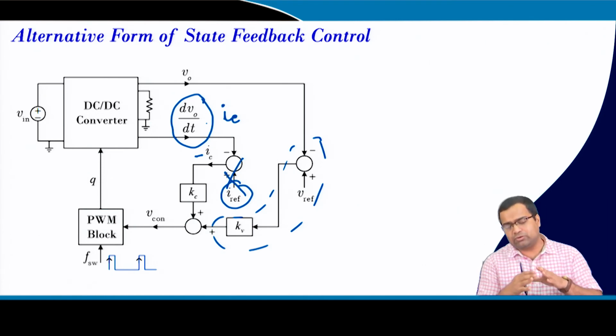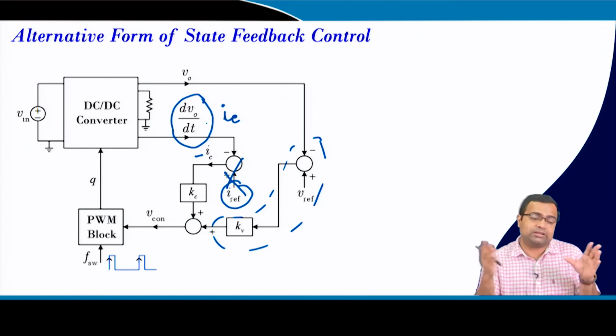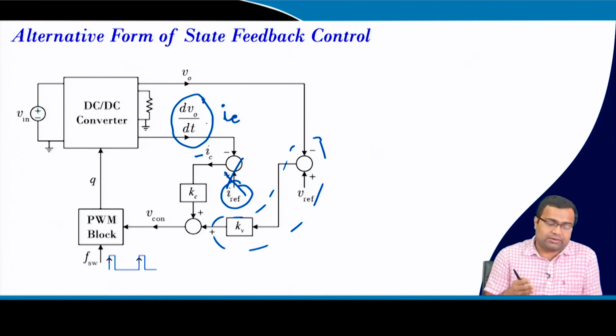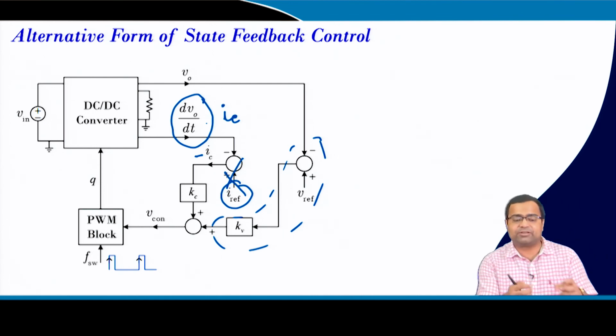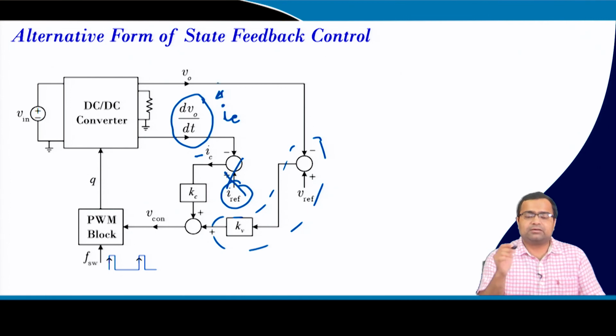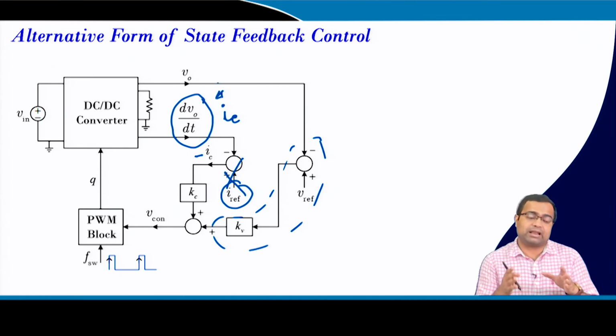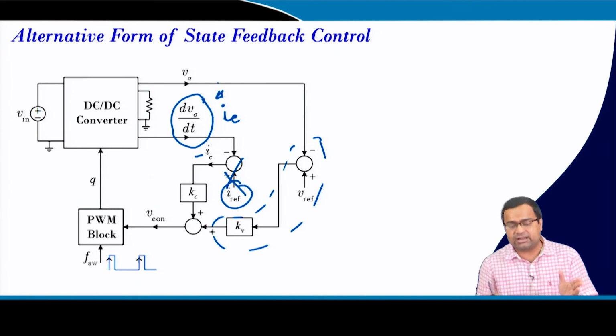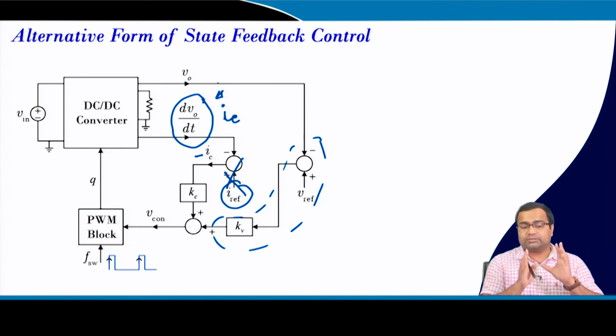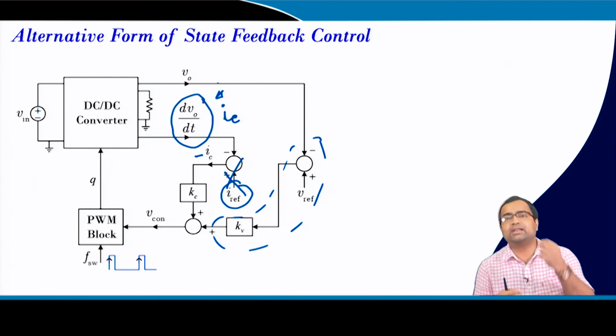And if we put a low pass filter, then we cannot capture the high frequency current information, because the low pass filter will attenuate it.